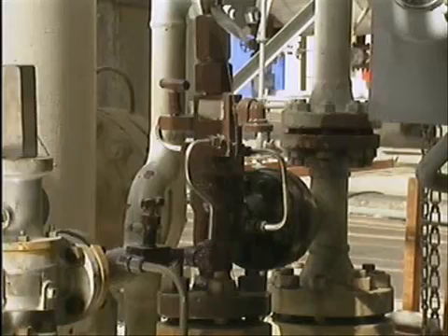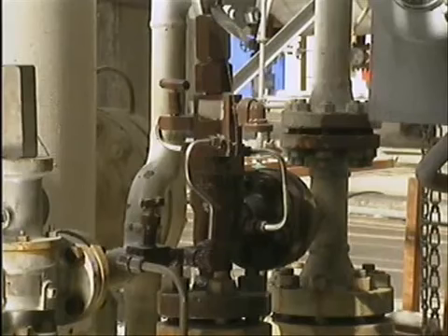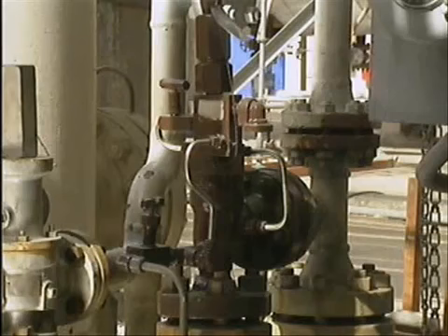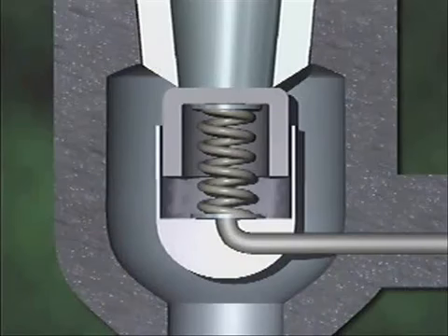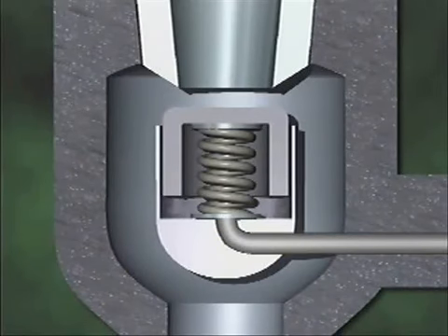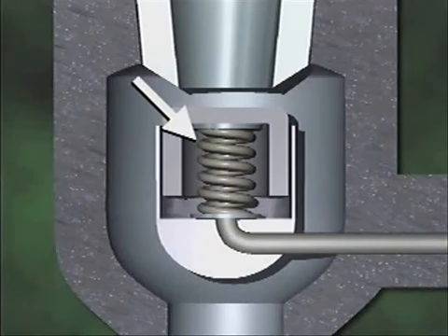Pilot-actuated relief valves, however, can be isolated from a system because they're not a primary part of the system safeguards. So, the pilot-actuated relief valves can be used and then repaired if necessary without having to shut down the system. The disc opens downward, allowing the steam to escape through the outlet at the upper part of the valve body. Also, in this example, the spring is placed below the disc.